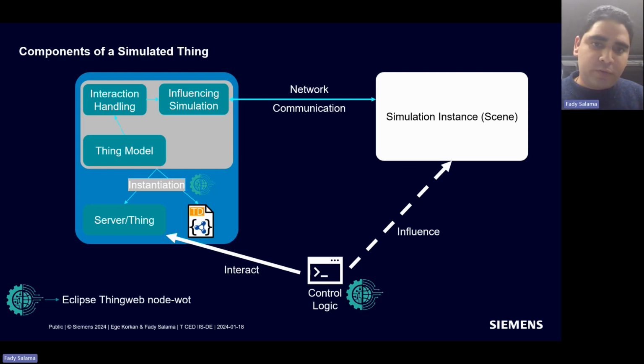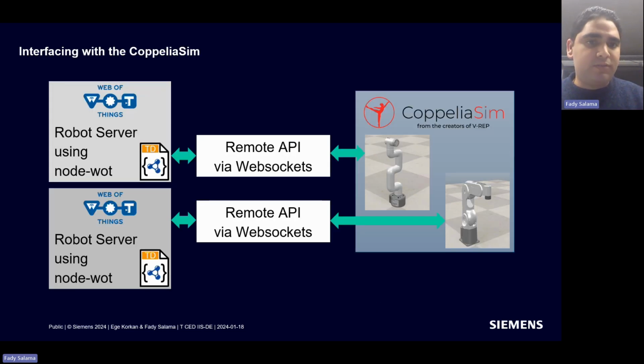So that's how it generally looks. And of course, the simulation software can change. Even the scripting API stack can change, but this is the framework itself and how the concept looks. In our case, we have the simulation software as CoppeliaSim, simply because it has a very good facility for generating robots from URDF, as well as a good remote API that can be used from the outside by any other stack.